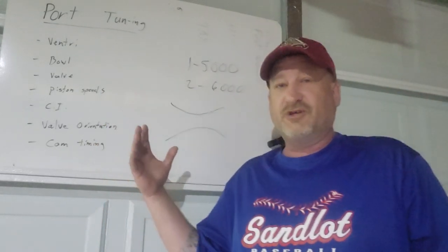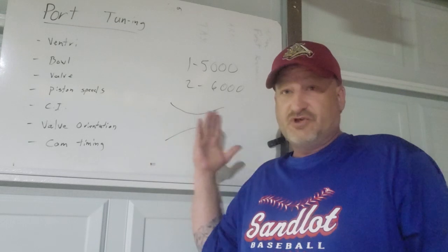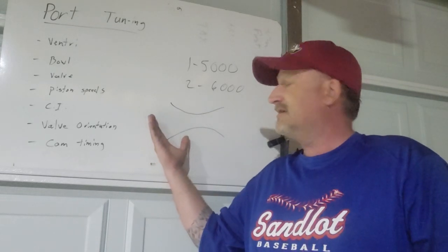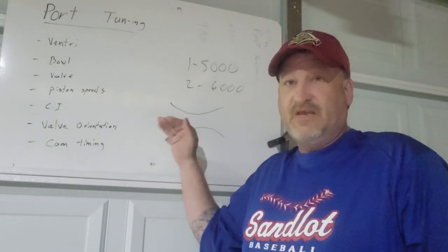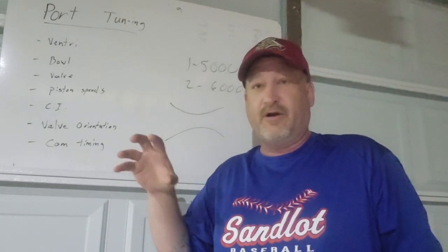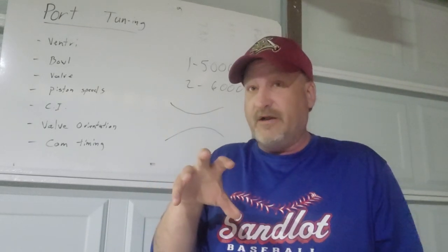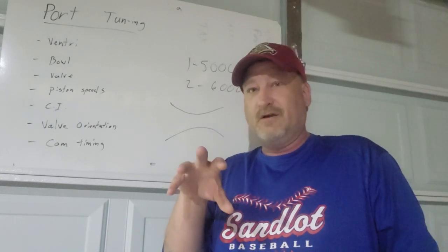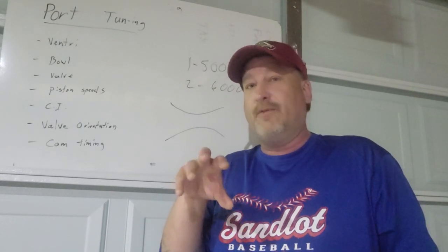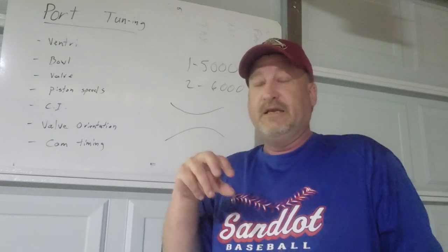So reducing the reversion as short as you possibly can with an intake system allows the entire system to ram the force and the pressure within the bowl area. So the larger the bowl area, the more volume of the next intake charge is available at lower lift numbers.